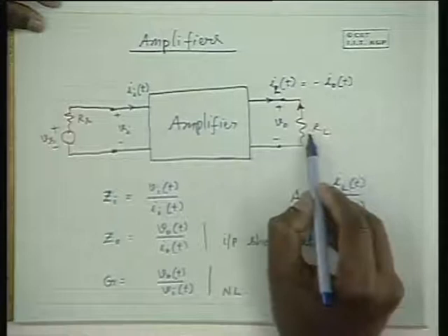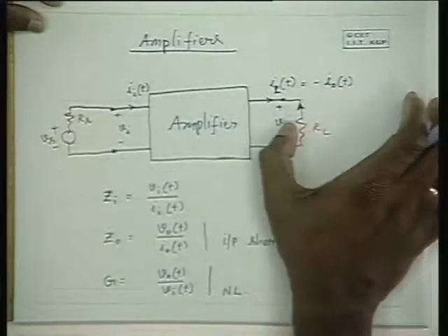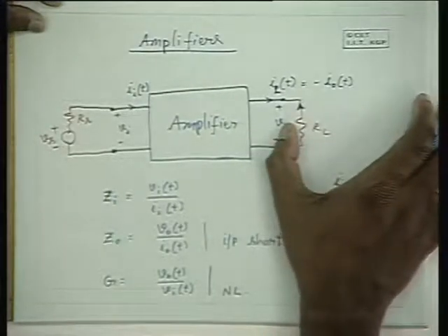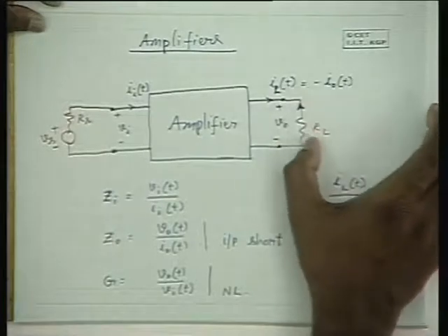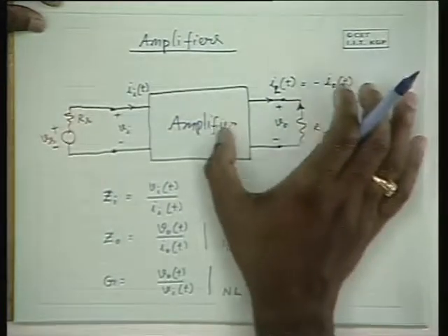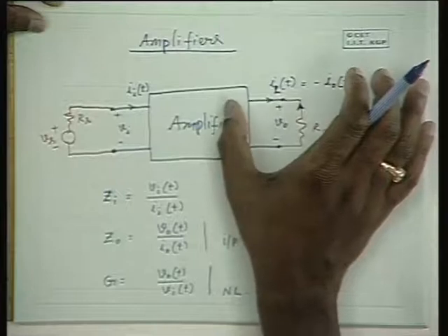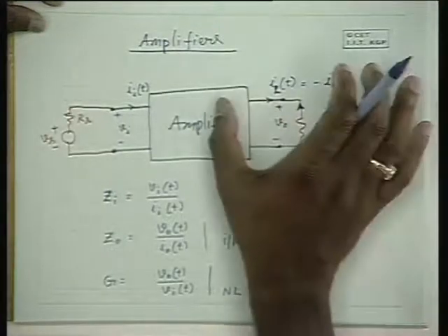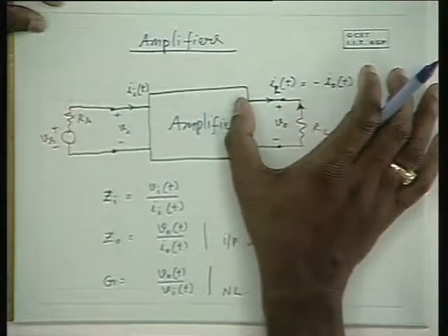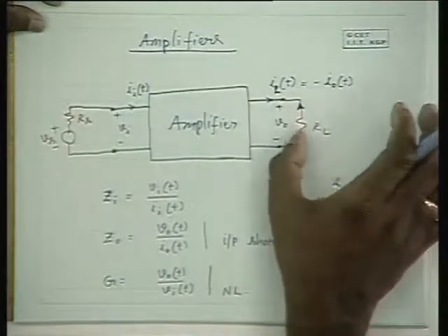Gain under loaded condition, because Vo/T is the output voltage when load is there. If it is not there, this Vo/T would be different. So, when load is included, that G times Vi gets divided between RL and Ro, and that is what is Vo/T when load is there.